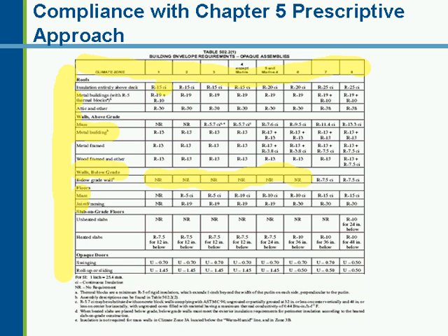And in that case, for mass floors, really the only place to put that insulation is going to be continuous. So the mass floor row will have a CI next to all the insulation R values, and joist framing, they will assume the insulation is going to be placed between framing. So that is the R19s, for example, will be assumed between framing.